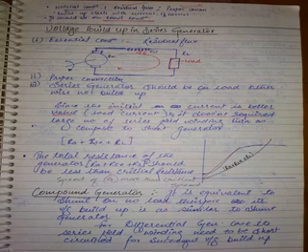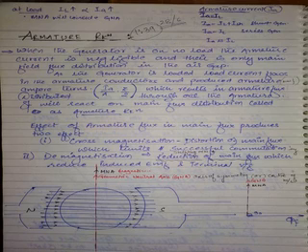Next. What is the ISH value? It is V by RSH. This value is low and nearly constant compared to IL. Yes or no? Compared with IL, for a machine of rating 20 amperes or 30 amperes or 50 amperes, as the load increases or decreases, ISH remains the same at 1 ampere only. So if IA is 50, then 50 is equal to IL 49 plus 1. Finally, what I want to convey is that ISH is a low value compared to IL.